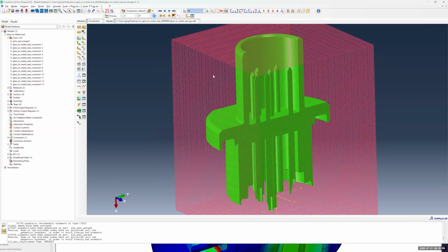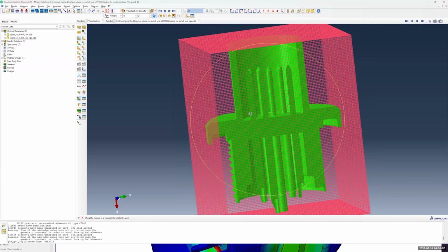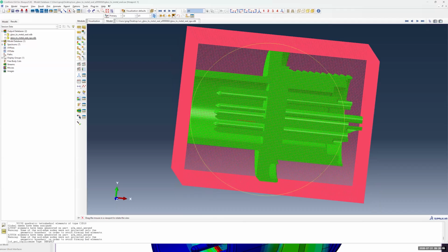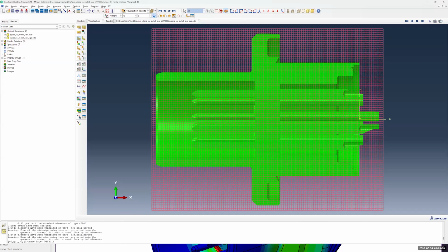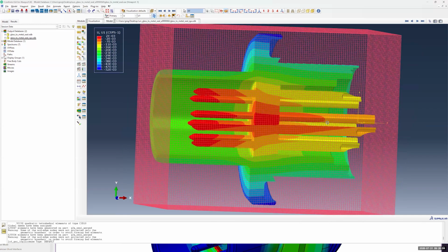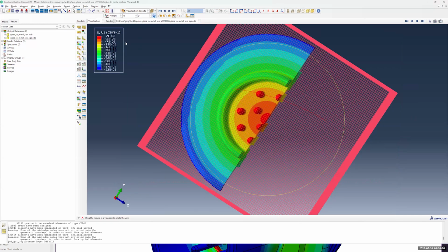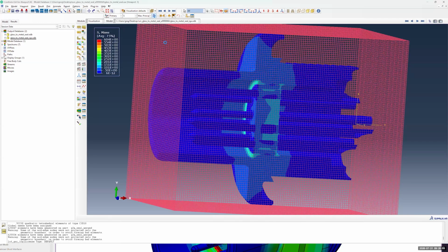So this is an initial release, so we are trying to work out some kinks in some of the user displays. But if we look here, you can see my background grid on top of my simulation result. I've created a cylindrical coordinate system. So here, looking at the radial displacement of my header geometry at the final time step, and then, say, my stress. Maybe I want to look at the max principal stress.